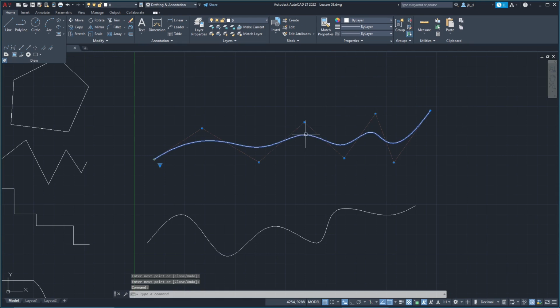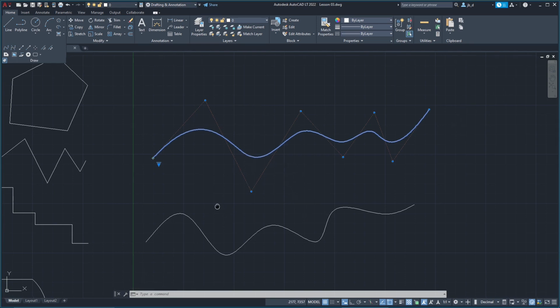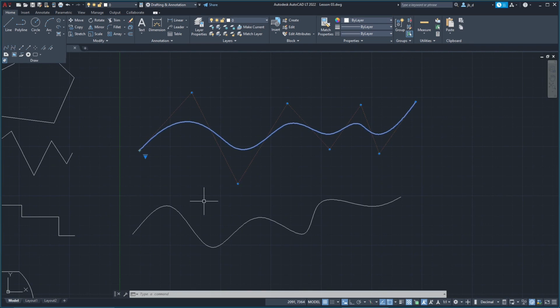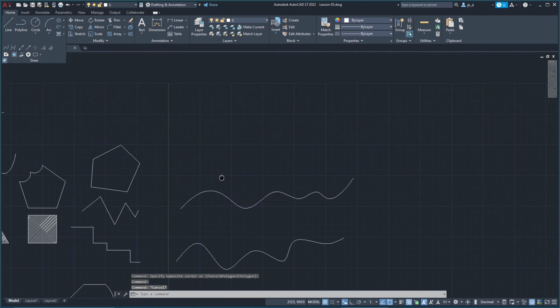But this time, if I select it, you can see that it's managed by these external points, external vertices. So these are not vertices or points that are inside, but they still control the curve, so they are called control vertices. And these two types, you can find also in Rhino 3D or Rhinoceros. And you can click here and change it anytime from fit to control vertices. So don't worry about it. You can always go back and change it.